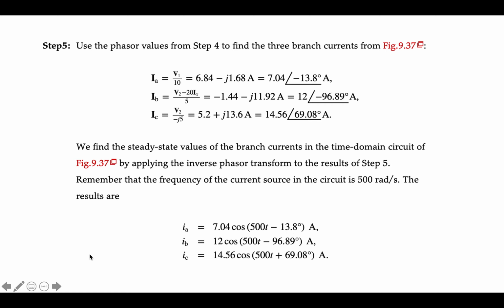And you do that for all three of the values that were requested in the problem. So no deep thought involved in going back and forth from time domain to phasor domain. It's just a simple matter of finding the magnitude, finding the phase, being sure you have a cosine function, and realizing that within a circuit all of your frequencies will be the same.